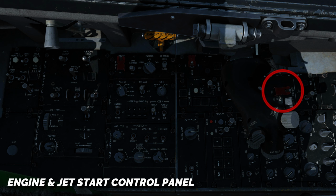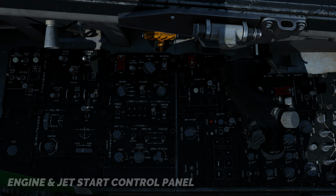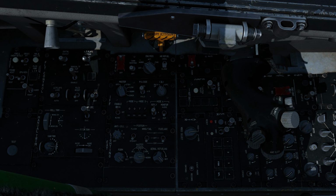Engine control is in the normal position. The pilot can select two modes of operation: primary and secondary. Primary mode provides unrestricted engine operation throughout the entire flight envelope. Main engine fuel flow is controlled by the DEC when operating in primary mode, and the MEC fuel flow control is in standby mode. Secondary mode is activated manually by placing the engine control switch in the secondary position, or if the DEC detects certain failures.